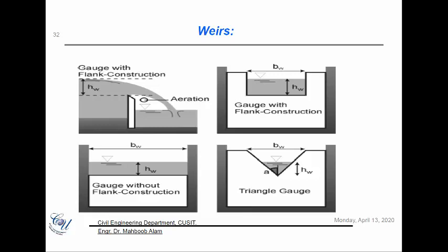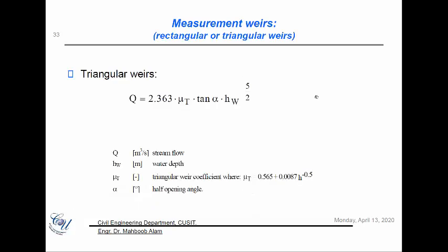There are then other installations, the weirs for example, the spillways or other gauges where we can compute the discharge, because we know, for example when we are looking at this picture, that there is a consistent depth of water, we know the height of this structure, we know the width of that structure, so we have a fairly good idea of what the area is, and then we just compute the velocity and we can compute the discharge along the river. So weirs are another way of calculating the discharge.